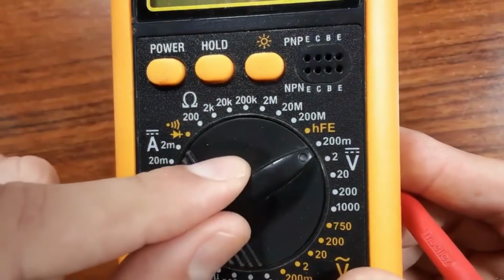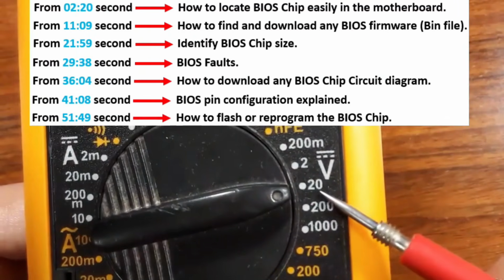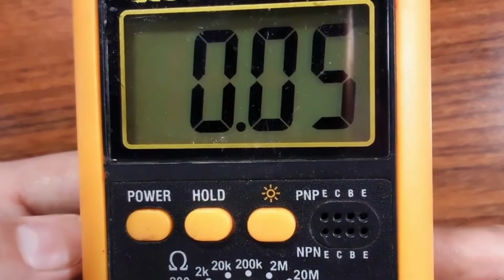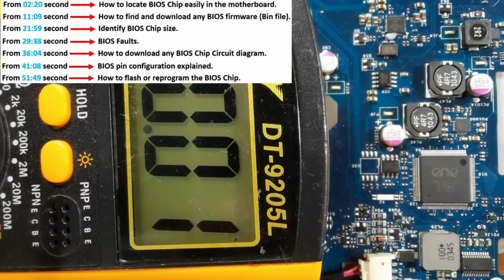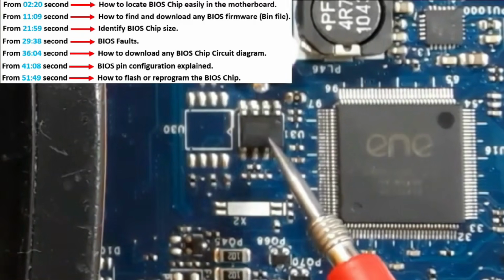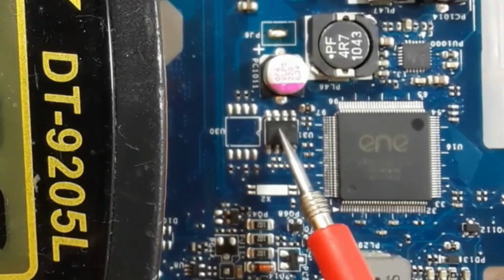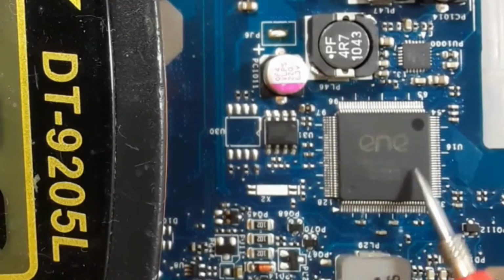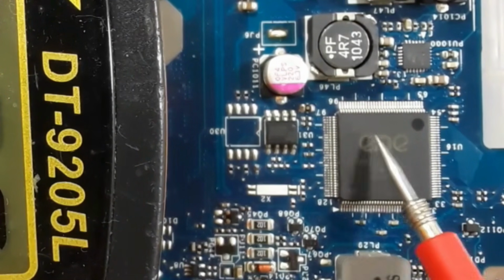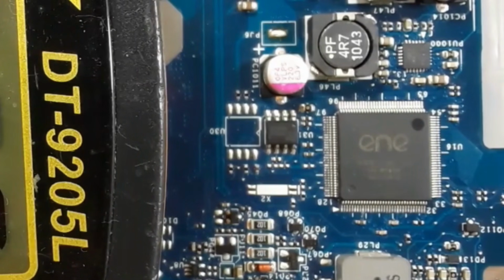So first, we should put the multimeter to the DC voltage to 20 volts and then press the power button. As you can see here, for example, in this motherboard, this is the BIOS chip with 8 pins. Okay, usually the BIOS is near the super IO, or near the ICH.